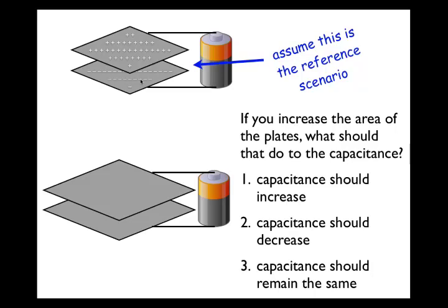It gets even harder to put the third electron on the plate, the fourth, the fifth, and it's increasing in difficulty. And at some point, the battery no longer provides enough energy to pack additional electrons onto that bottom plate, and at that point the capacitor is considered to be fully charged for the arrangement that it's currently in.